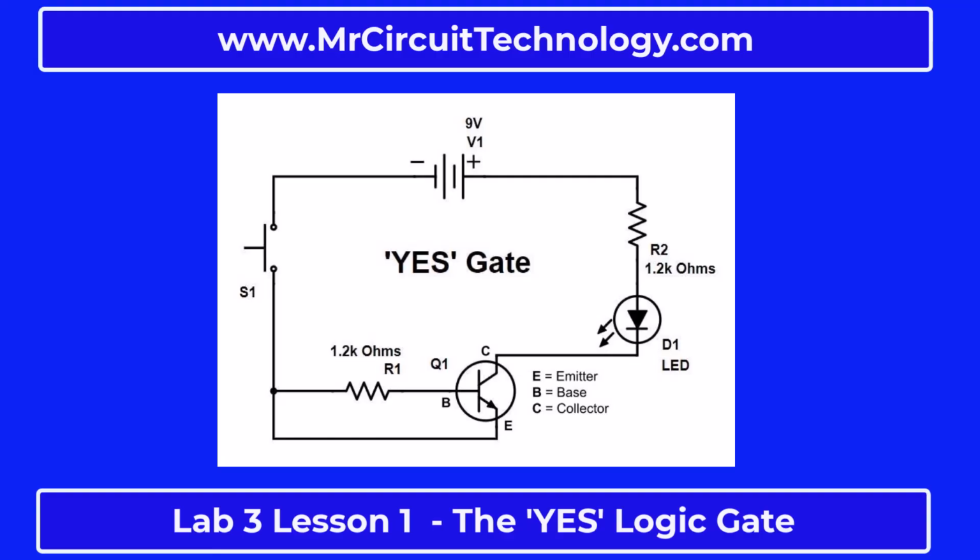Let's talk about the transistor. Remember that when a transistor is forward biased, it means that it has all the correct voltages on its pins to allow electron current to flow through it. An engineer designed this circuit such that 2 resistors are in the right values to cause the correct voltages to be on each pin of the transistor when you press switch S1. Note that the arrow on the transistor symbol actually points in the opposite direction of the current flow.